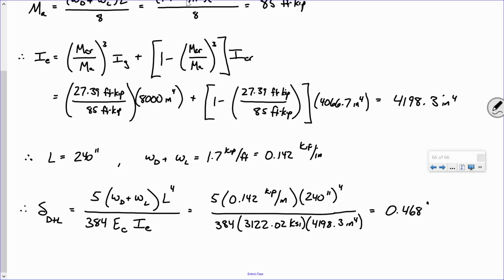You can't do that because you won't be coupling this load and this moment of inertia properly. This moment of inertia corresponds to the total amount of load. Do you see what I mean? If we were going along your path, we'd have to use just that much moment in this moment of inertia up here, but then we wouldn't be representing how much of the beam is truly cracked. Does that make sense?